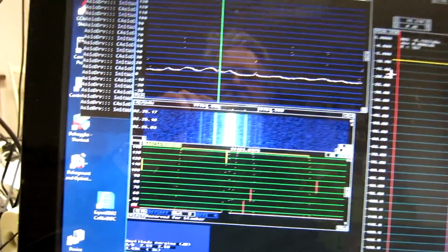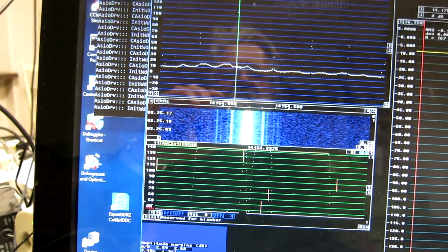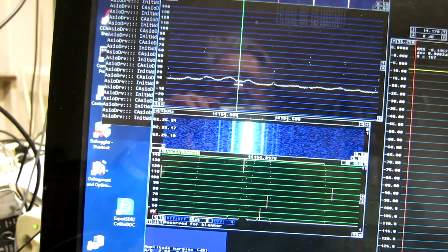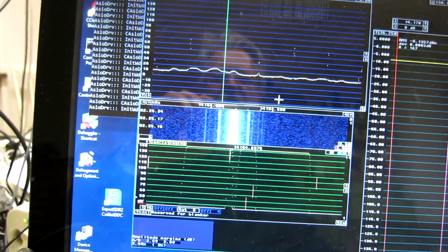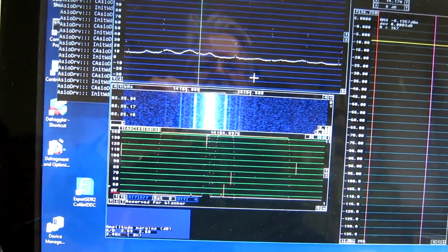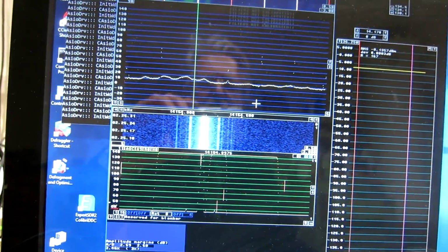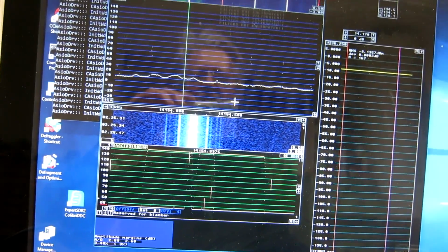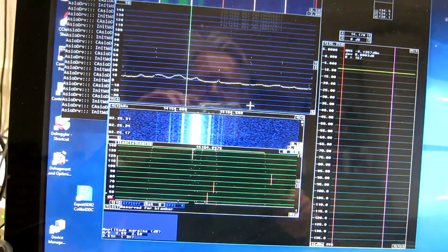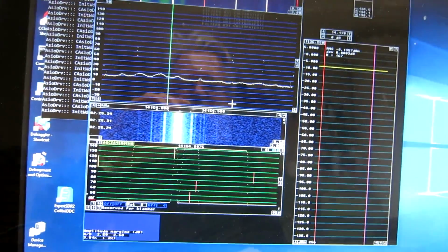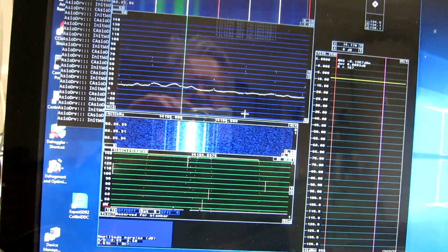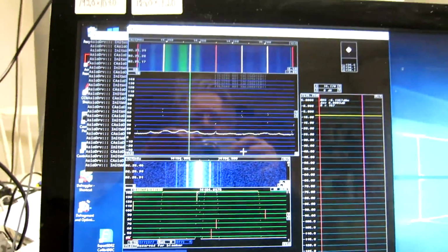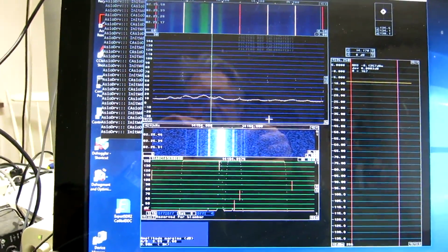8.1, well. And the frequency is not at the optimum place and not at the worst place in the baseband spectrum. The Asus Xonar has an ugly noise floor. This would probably be fairly easy to fix by suitable decoupling capacitors, but that is not something that I'm going to spend my time on.